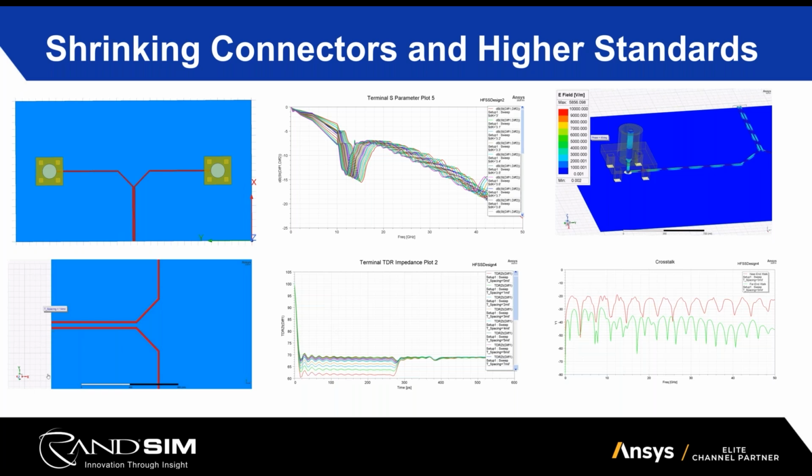So what I also did is I ran a similar scan of the differential trace routing, changing the distance in between them, so I would be able to look at the impedance. So as we can see, we can once again look at our impedance graph shown below and see which impedance is going to be best suited for what we are looking for.